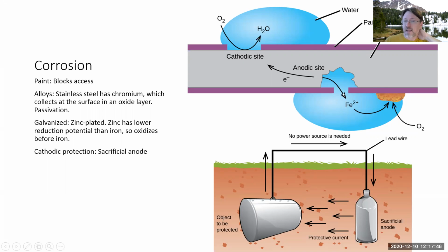And because the dissolution of the iron 2+ and the combining with O2 to form the rust happen at different locations in this deposition process, you end up getting this pitting and then a growth of rust on it. And this is why rusting or corrosion of iron tends to be so destructive. This is in contrast to how aluminum, for example, acts. When you have aluminum reacting with oxygen in the air, then it forms a uniform thin layer of aluminum oxide on the surface.